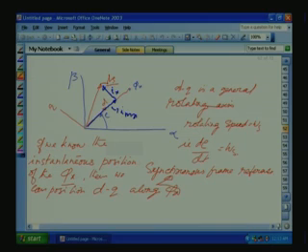So, we want a general rotating reference frame dq such that D should always be placed along the psi r axis. While doing so, the stator space phasor current Is we can split along psi r and orthogonal to it.